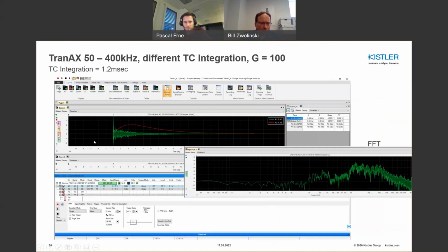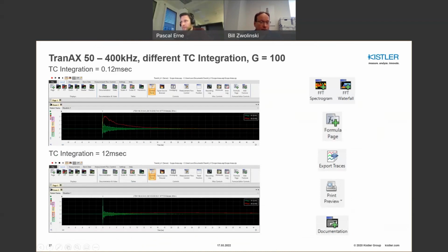With this Elsys system, a pretty intuitive system, you have a raw AE signal in the green, and the RMS output in the red, which I showed you. And this is the FFT of that signal. You can see here, it's a logarithmic scale, but somewhere around 50 kilohertz to 1 megahertz, you're seeing quite a bit of signal energy. What we used here was just a simple pencil break test, which is fairly common to generate broadband acoustic excitations.